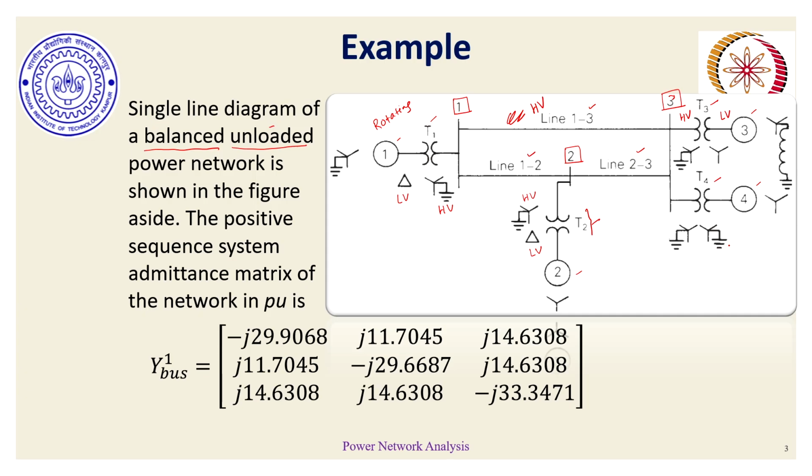The reason I am emphasizing all this is that when we have to analyze some fault, balanced or unbalanced, on this three-phase balanced power network, the connections of these transformers are going to significantly affect the zero sequence network, or the zero sequence diagram, of the corresponding network.